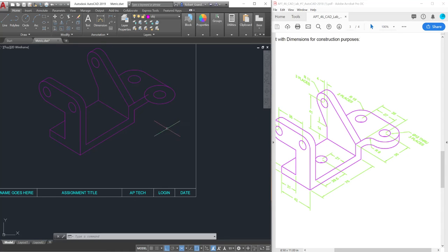I cannot use the fillet command in isodraft mode, because if you do, you do not end up with elliptical arcs. You instead end up with circular arcs. So I'm going to go ahead instead start my process by drawing it in the wrong location. I'll snap to the center here. And when it, oops, what did I do wrong there? I didn't invoke my isocircle option. So make certain you invoke the isocircle option. Select your snap point, and this is going to be a radius of 8, so I'll just type in 8.